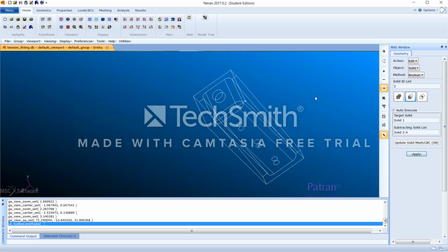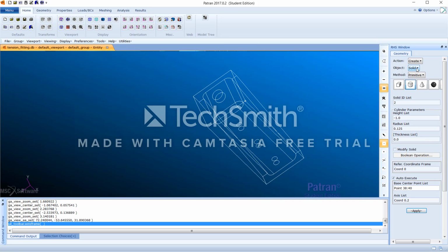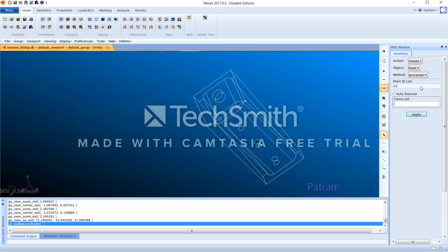Now we're going to create a cylinder to imprint tension fitting. First of all, we have to create a point in the center of the large hole. For this, set action as create, object as point, and method as arc center. Select the large hole edge and apply it.